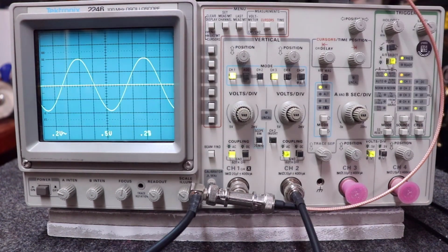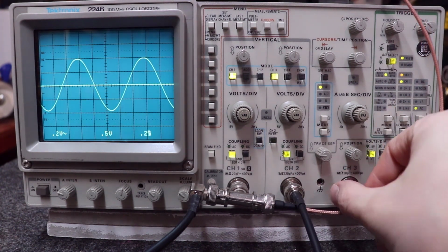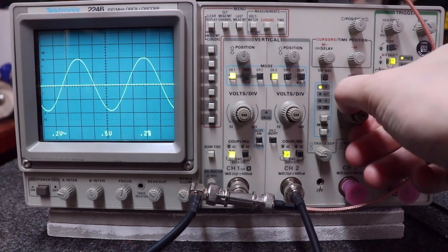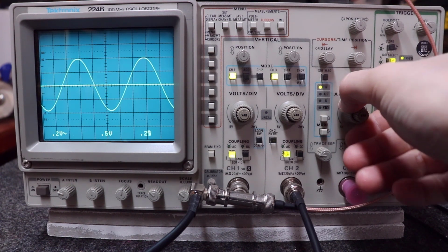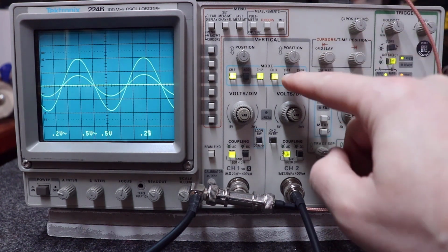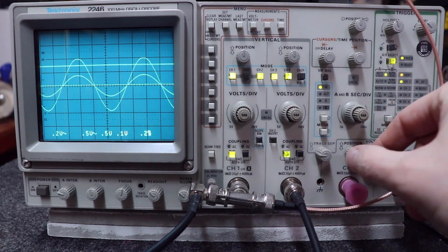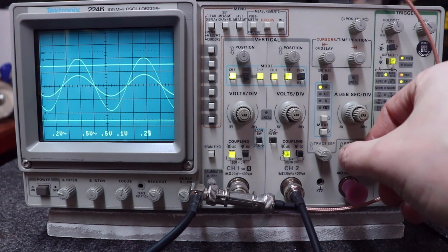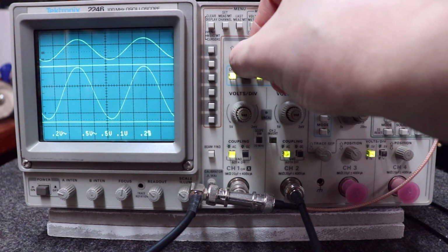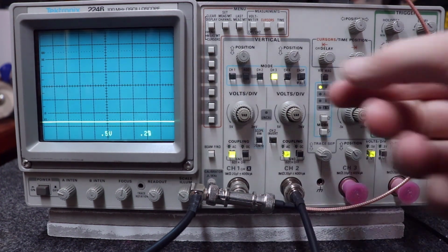In other words, we just have a signal going in. There is no varying amplitude because it's right here. There's nothing plugged into it at all, right? But one thing to notice about channels 3, 4, and 2, they all share the same time base, okay? So if I turn channel 2 on, and I've got 3 channels going. If I turn channel 4 on, I've got 4 channels going. And by the way, you can use different position knobs here to put the different channels where you want them. Like you could put one down here. Maybe you put one up here. You can just put them on the screen where you want them to be able to look and see at different things. But what I was just showing you here, let's just say we only show channel 3 here.